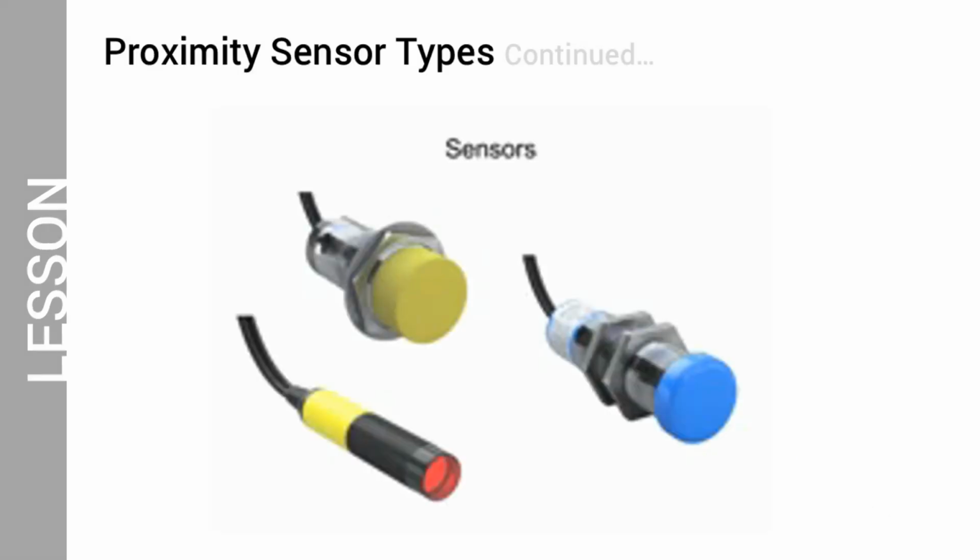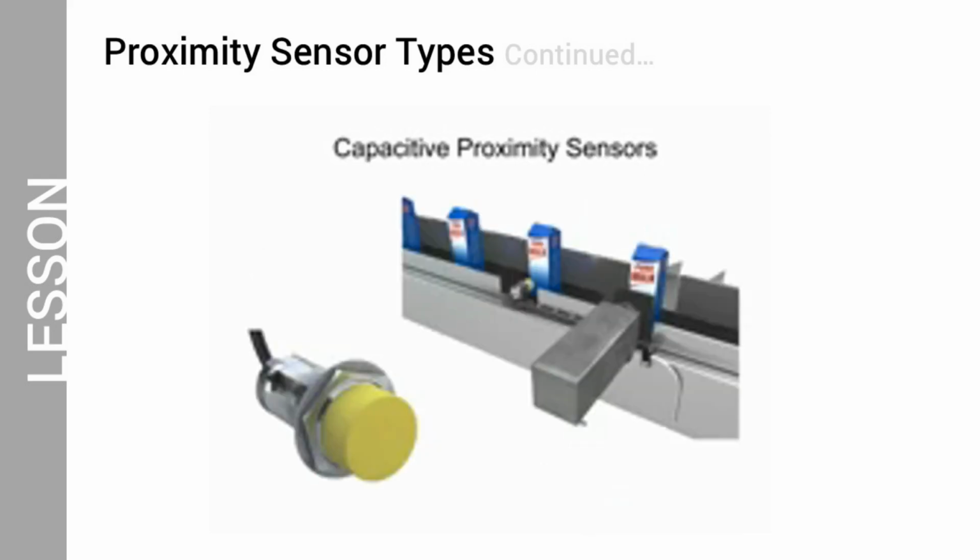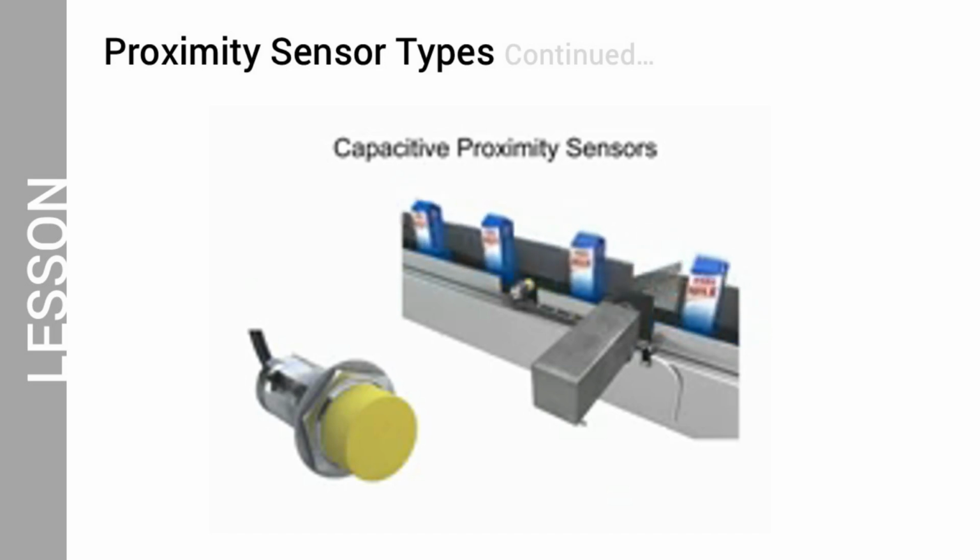So, starting off, we have an inductive proximity sensor, which we talked about is good for gauging distance. As material comes up to it, flux lines change and the inductance changes. For capacitive sensors, because we can get information from changes in dielectric, we can use them to judge whether material is exactly as we expect or not, causing some rejection for bad materials.